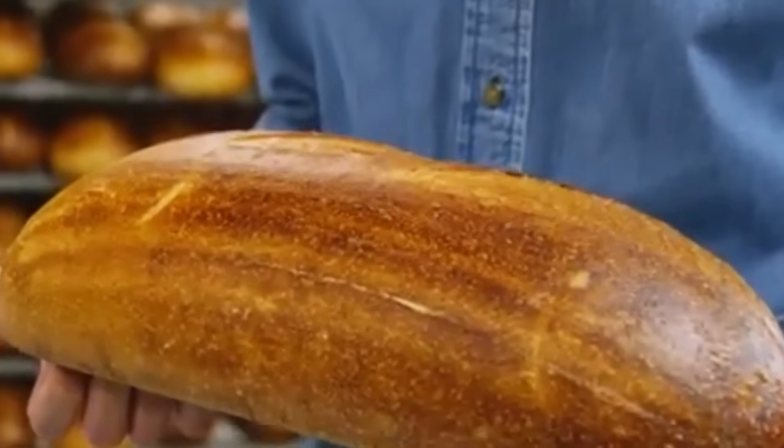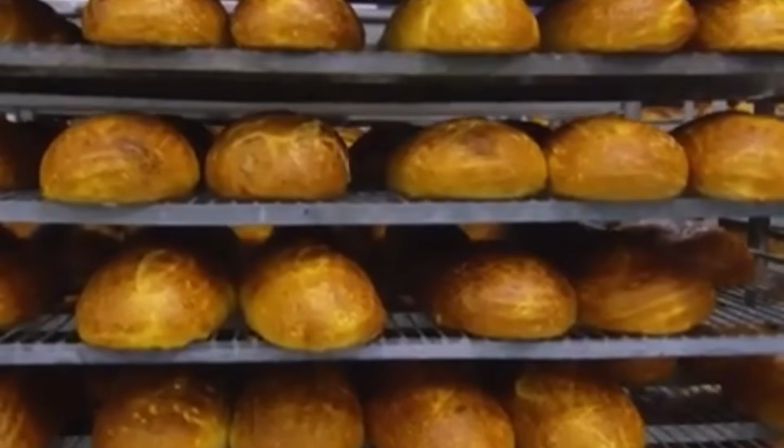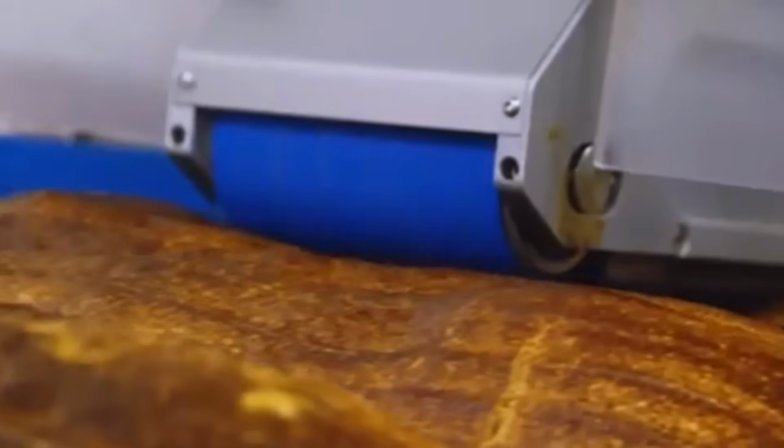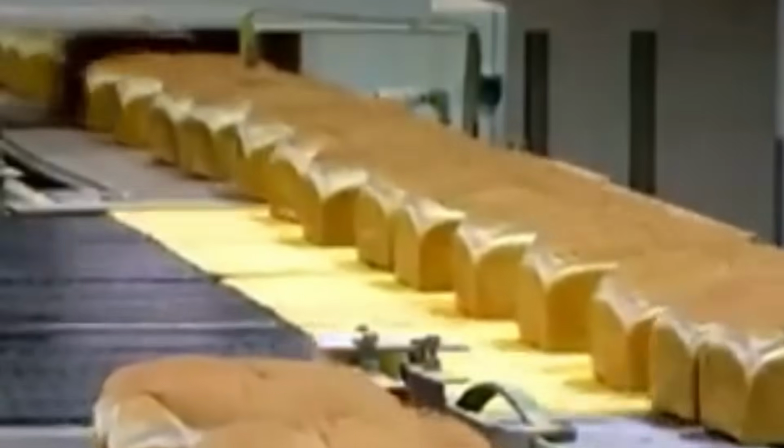The baking process unfolds in stages. First comes expansion, where gases expand, alcohols evaporate, and enzymes break down residual sugars. Then comes gelatinization, as starches swell and set. Finally, Maillard reactions begin on the surface, turning the pale, supple dough into a rich, caramel-toned crust. The belt moves at a steady pace, calibrated so that by the time each loaf exits the last zone, it has reached the exact internal temperature required for complete bake, usually just over 96 degrees at the core.